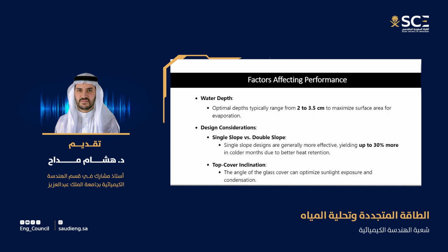How much is the water depth? Some people suggest from the research, you should not allow the water to go more than 2 to 3.5 centimeter in depth inside your tank. That means you have to have a huge space of land and vast area of land to be only utilized for this system. You cannot have high depth or very large depth of the water inside the tank.